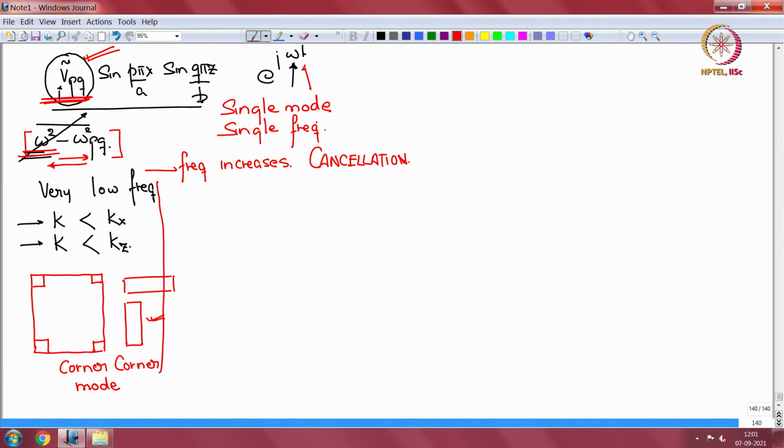So we started off with this plate over here, case 1 at very low frequencies. There is this panel which I have drawn. You can take it more rectangular, A is bigger than B or B bigger than A, and at very low frequencies Kx overwhelms K, Kz overwhelms K, and therefore there is very heavy cancellation and only the corners remain uncancelled.